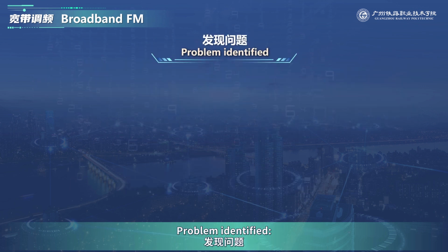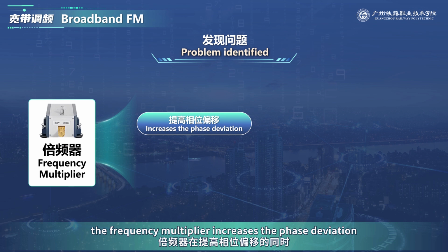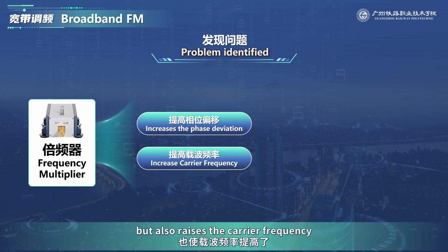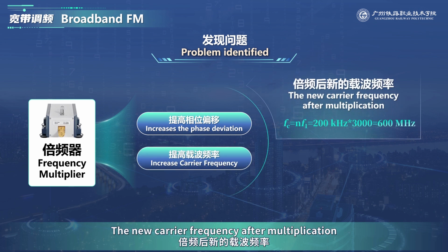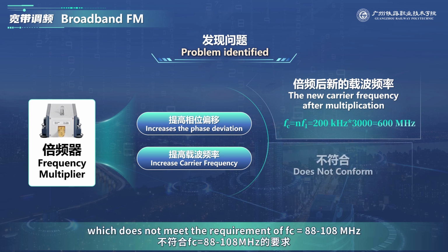Problem identified. So here is the problem. The frequency multiplier increases the phase deviation, but also raises the carrier frequency. The new carrier frequency after multiplication, N f1, is as high as 600 MHz, which does not meet the requirement of fc equals 88 to 108 MHz.